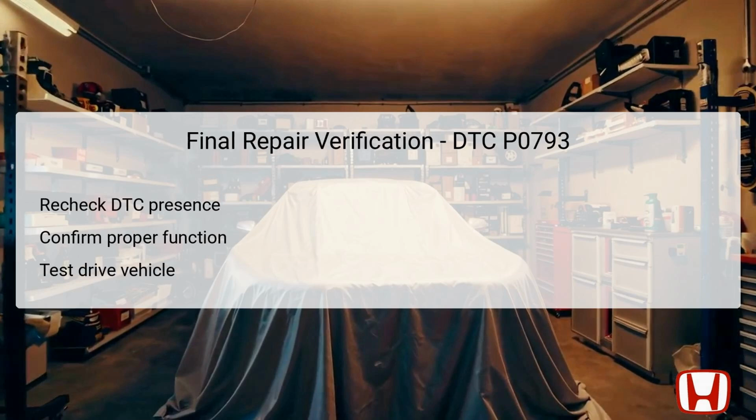After completing all necessary repairs and troubleshooting steps, it is crucial to perform a final verification. Reconnect the relevant connections and use the Honda Diagnostic System, HDS, to check if DTC P0793 is still present. Ensure that all necessary data has been cleared first. A successful repair would be indicated by the absence of the DTC upon rechecking.